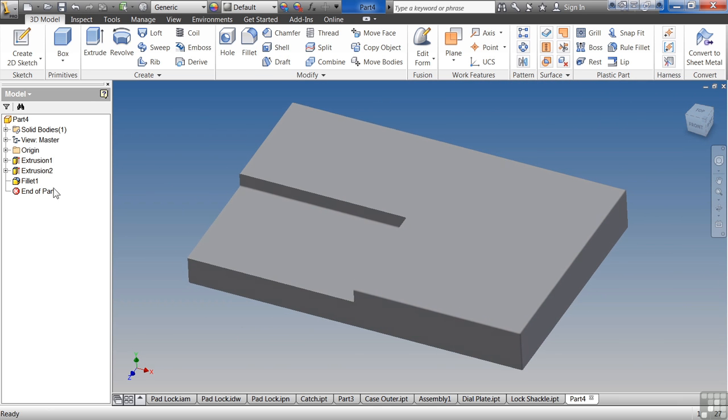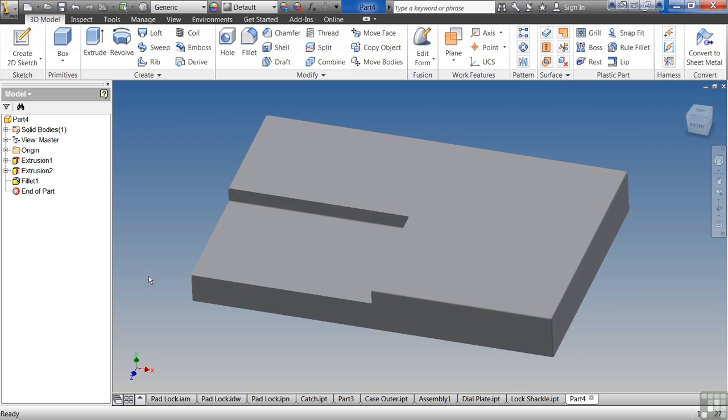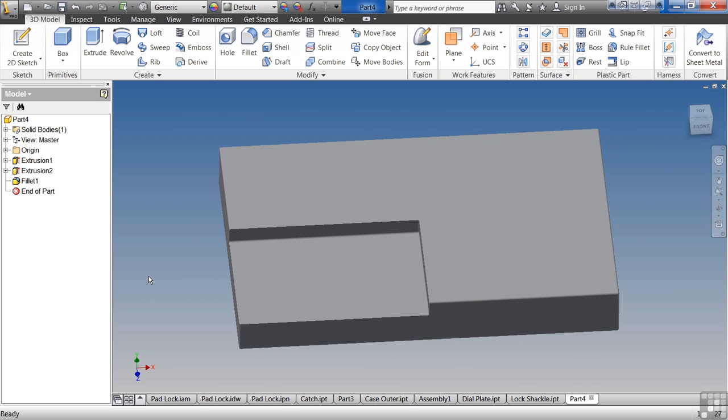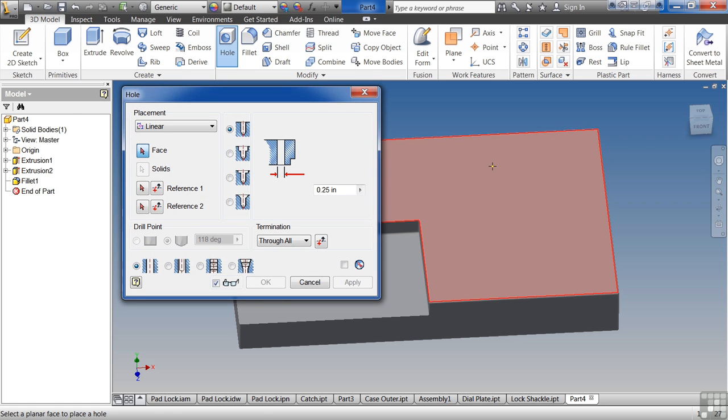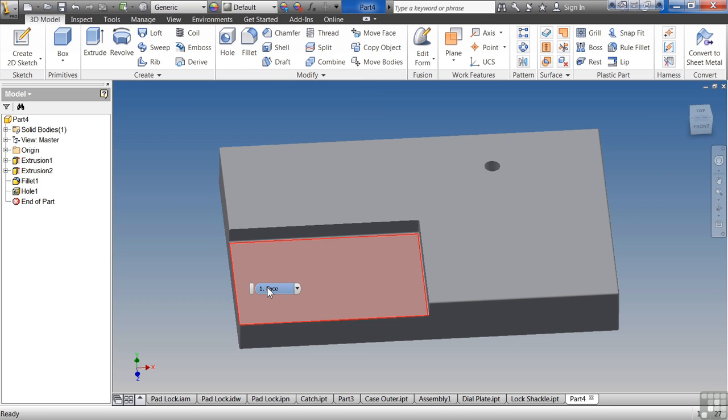And if I want, I can go back and I can add additional fillets and chamfers and actually create my part. But that's your first parametric part. Very simple. If you want to play around with it, maybe add a hole. The hole could be either a placed feature or a sketched feature, based on how you use it. Place a fillet, place a chamfer, place a hole. Do some real simple stuff just to get used to playing with parametric parts.